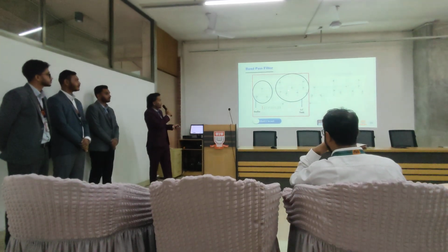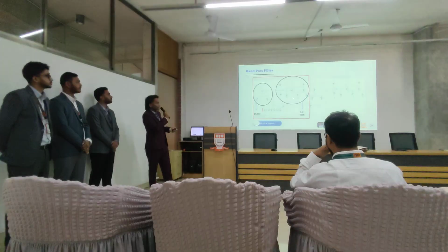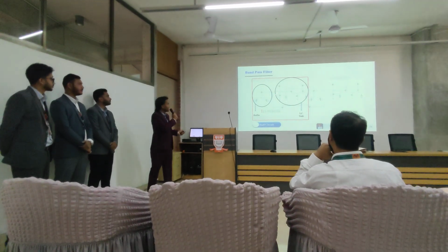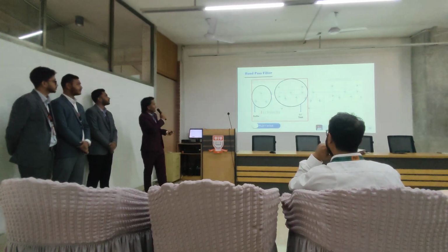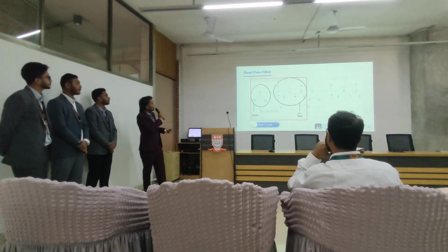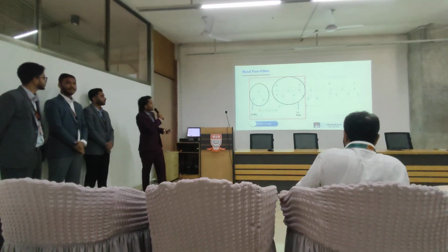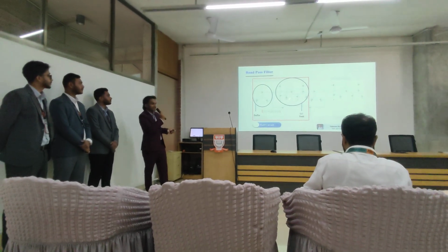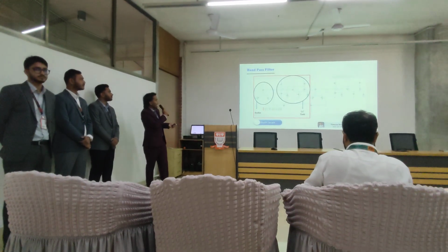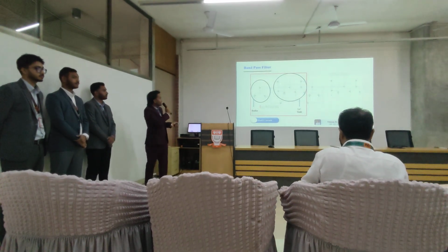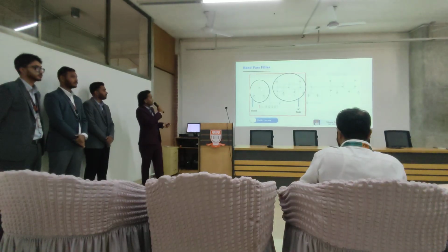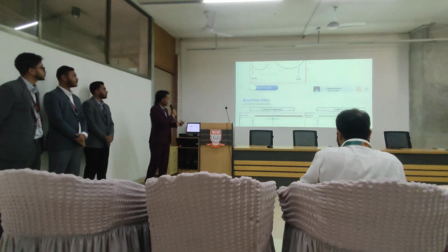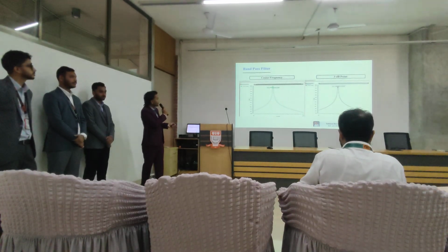We also have tunable functionality with this transistor, by which we can change the center frequency of our bandpass filter. Now you might ask why the current from this transistor doesn't also escape into this other transistor. We have designed this as a source follower buffer, whose gate actually works like an open circuit. It also allows us to isolate our LC tank so that a heavy load doesn't destroy our Q factor and also detune our frequency.